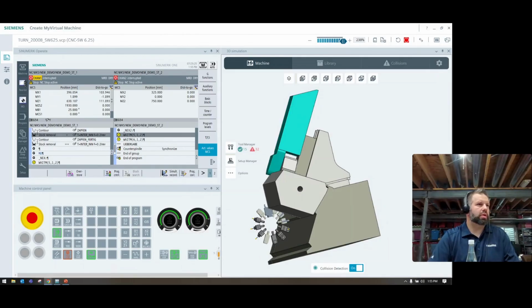They wanted the chip load control as well as the surface finish of a turned surface, so they didn't want to mill it, and it was on a machine that wasn't even a lathe, right? And to have a boring head for a 2 foot diameter bore just wasn't practical. I will say from experience, where the limitations are is the speed of your axes, right?